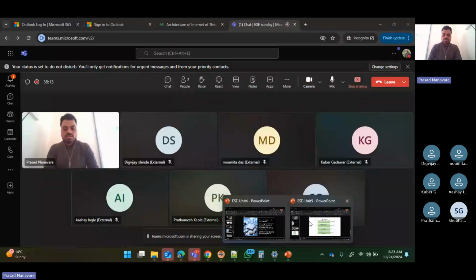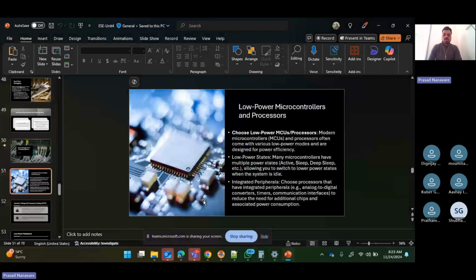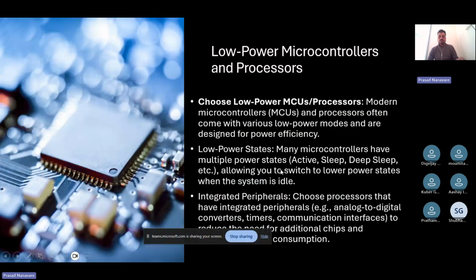So something called RTC works. RTC is a real time clock, and this real time clock is an IC basically. As long as you're giving power to that IC, it will retain the states. But once the power is lost, it's like a RAM: when the power is lost, the data won't be retained. So there is a cell in your computer, and that cell keeps delivering the power to this RTC.